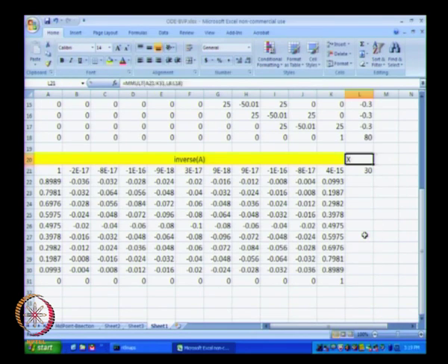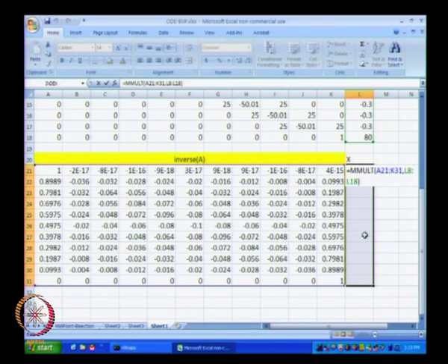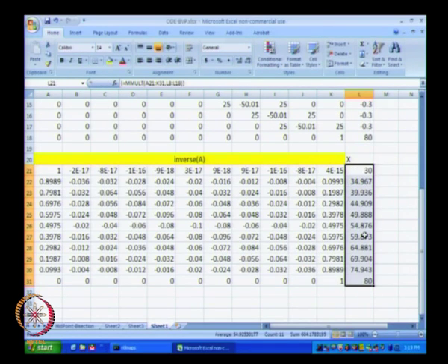And this x we can't copy paste. What we need to do is select the 11 dimensional vector, press F2 and then press Control Shift Enter, and this will give us the overall temperature.